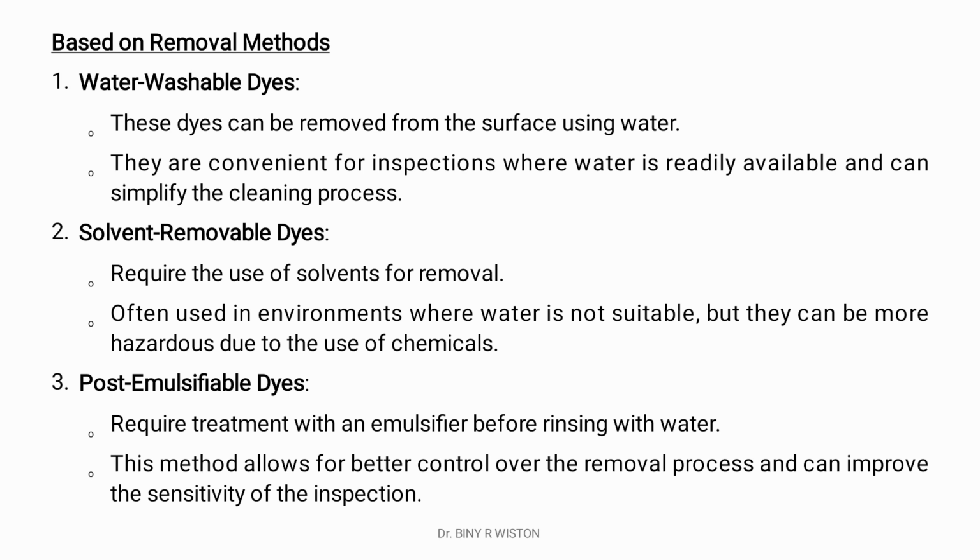They are convenient for inspection where water is readily available and can simplify the cleaning process. Solvent removable dyes require the use of solvent for removal and are often used in environments where water is not suitable, but they can be more hazardous due to the use of chemicals.